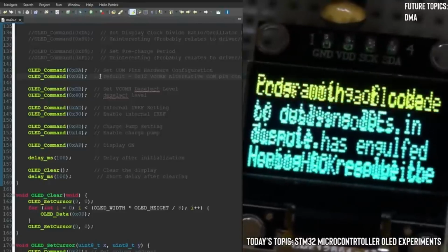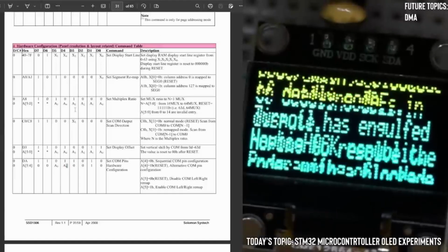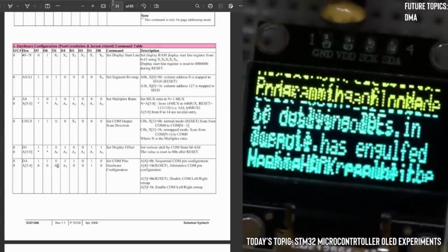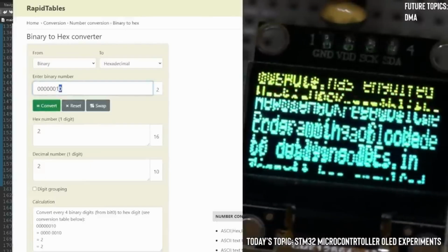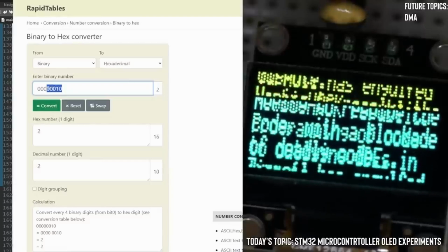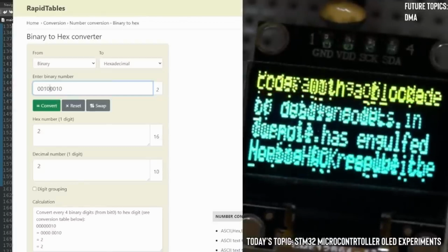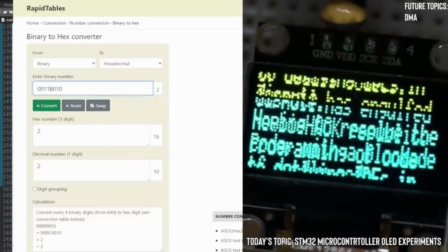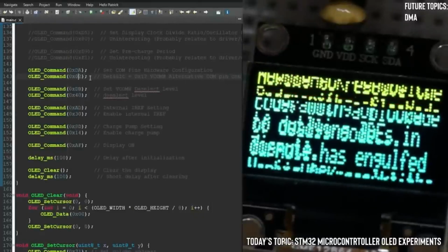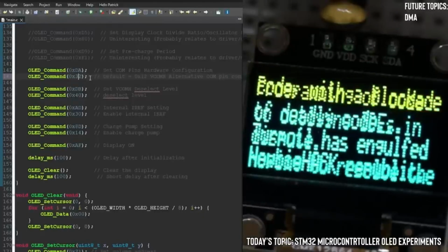All right, let's go back to the default. This is interesting. So what we can do is, oh wait, we didn't try the other one either, did we? So we can try a 1 here to see what happens. So this is 0, 1, 2, 3, 4. So we want to change to 5, and we want to put back what we had in 4. So that would be hex number 32. So it's always a 2. Always has a 2 there. It's either 12, 02, or 32.